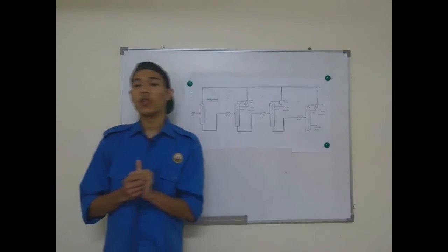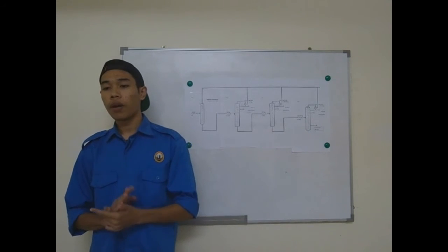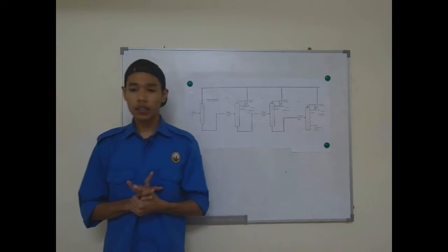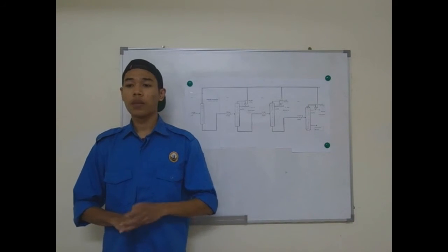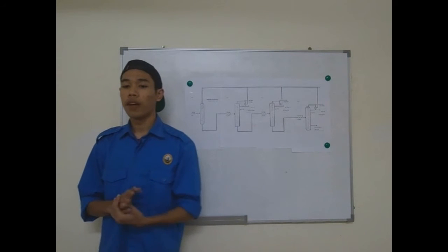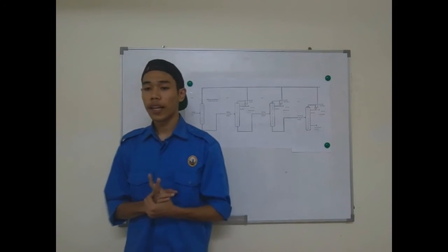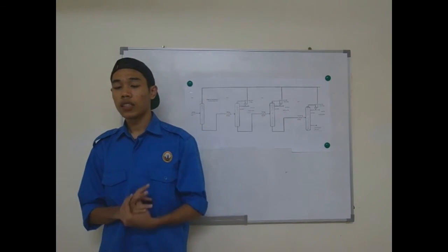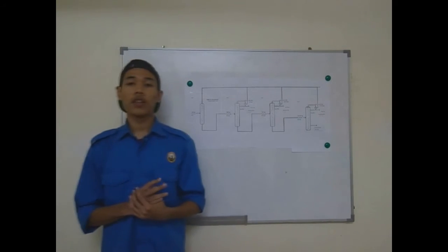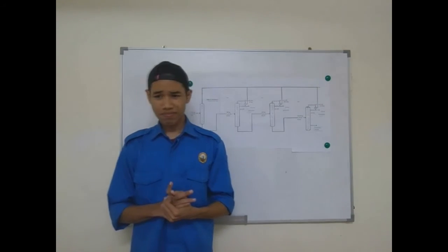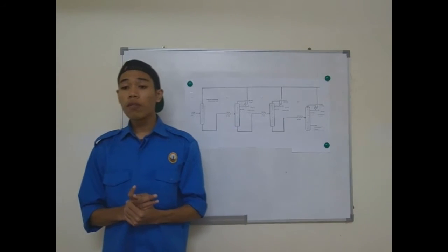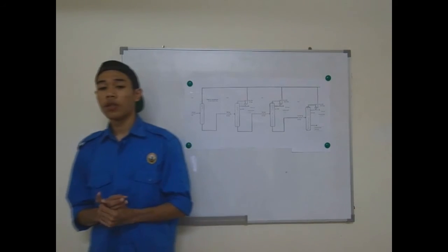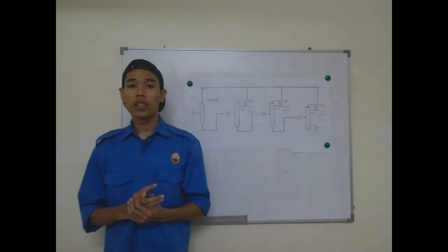Okay, lastly for the process of catalyst, there is fatty alcohol polishing. Fatty alcohol polishing is required to remove carbonyl group compounds that exist in the fatty alcohol product. Polishing can also remove color bodies, which usually consist of various unsaturated conjugated compounds. The color is removed by hydrogenation of those unsaturated compounds. The removal of unsaturated compounds helps to improve the storage stability of the product.